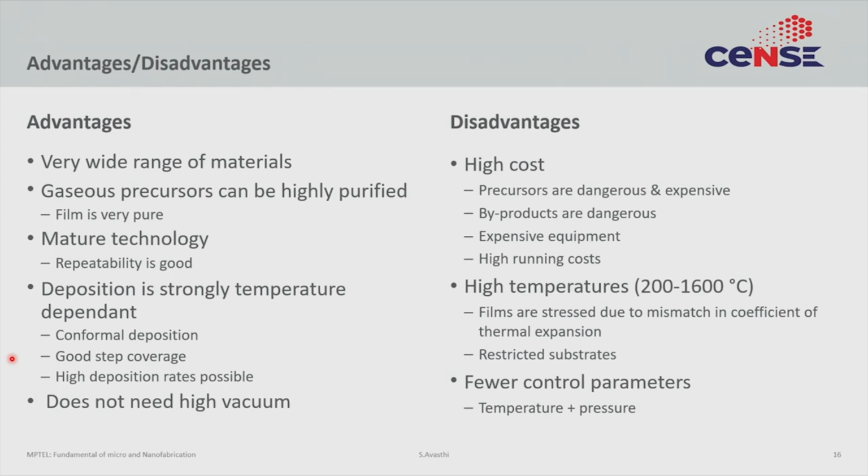And lastly, CVD is often a thermodynamically limited process, rarely a kinetically limited process. And that allows you to only have two parameters to really control the reaction. One is pressure, one is temperature. Other than these two, you don't really have a lever to control the way the reaction is occurring, and hence control the properties of the eventual film.